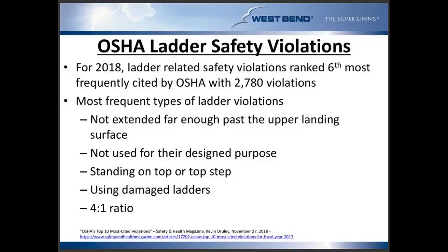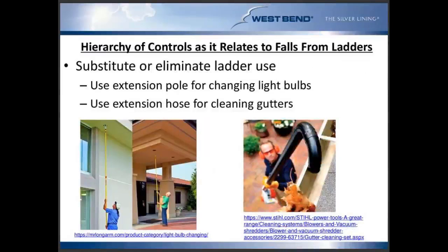Not being used for its designed purpose. So deviating from what the manufacturer originally designed that ladder to be used for and how to be used safely. Standing on the top or top step, using damaged ladders, and the 4-to-1 ratio, which again, we don't need to get into right now, but we will certainly cover in a few slides here. Just know that these are fairly easy for the OSHA folks to identify. It may not even require them to climb up onto a roof or even access a building. If they simply drive by a construction site, I think most of them can pretty much verify that somebody is not in compliance or an employer is not in compliance with these requirements.